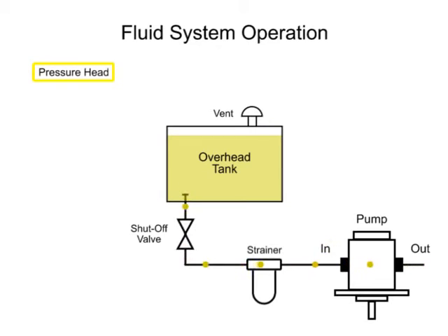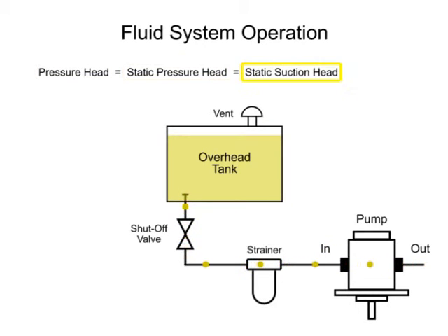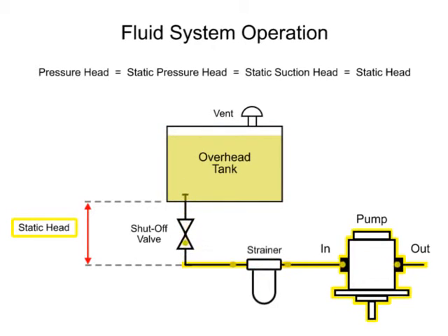or pressure head. Pressure head, also called static pressure head, static suction head, or static head, is created when the reservoir is placed at a height higher than the center line of the pump and is the measure of distance from the pump to the tank. This creates a positive inlet pressure and helps fluid flow to the pump.